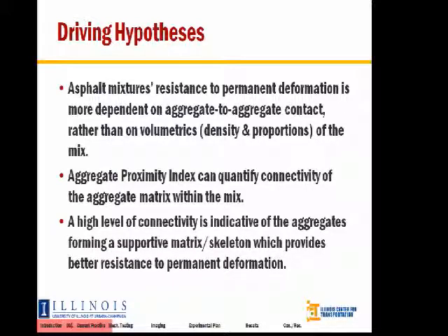So you can imagine, if you did not have a highly connected aggregate skeleton, as your traffic begins to load, it is going to slowly force the aggregate through that viscoelastic asphalt binder, if the aggregates are actually suspended within the asphalt binder. So the target is to increase the connectivity of that aggregate, and the binder is simply there to hold the aggregate in its place. But your resistance to this permanent deformation is going to come from your elastic aggregate that are directly in contact with one another in an ideal case.